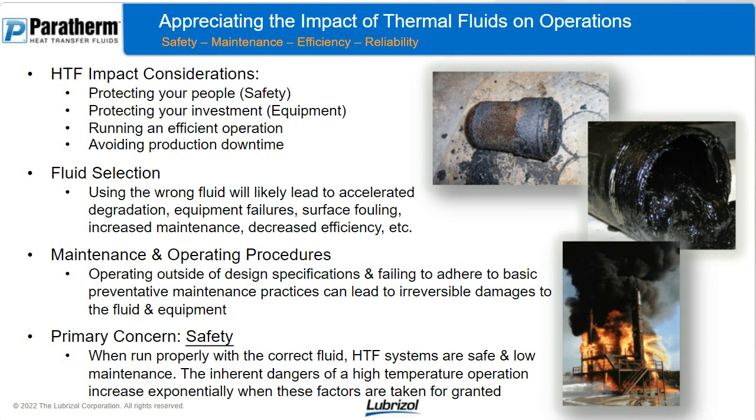There's a huge impact on fluid selection, and we're going to spend a little time on that moving forward. If you select the wrong fluid, and this is not a fluid brand or anything like that, this is the fluid type and the fluid quality and the attributes that we'll introduce moving forward. If you select the wrong fluid up front, it's going to be a catalyst for accelerated degradation, which ultimately leads to equipment failures, fouls the surfaces, increases maintenance, decreases efficiency, and causes safety problems.